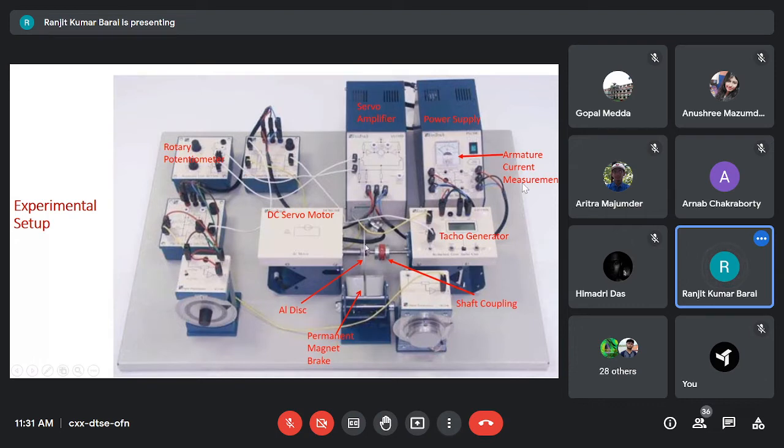so that when the magnet is moved in the downward direction, what will happen? The disc will enter the air gap more and more, up to this point. So it will cut more magnetic flux. And if we lift this magnet, the disc will come out from the air gap of this magnetic brake. So it will not cut any flux, and it will rotate freely.